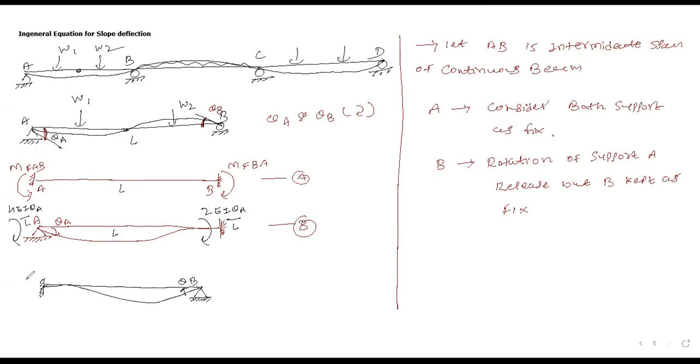So as we have discussed, you have some moment here and moment here. Whatever support is rotated by theta degree, we have 4EI theta B by L, and the opposite end will be half of that value. I hope it is clear to all of you. इतना clear है? Keep in mind, both rotations will be the same for both moments. Same way you have to write.